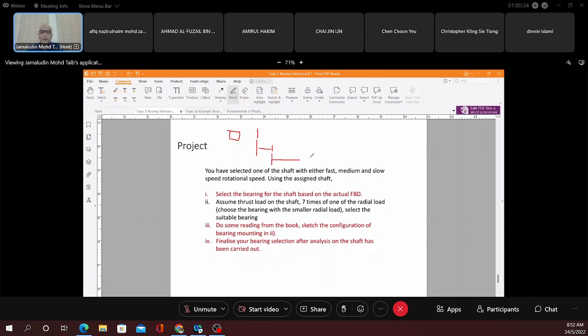For the gear manual calculation, one person will do this one, the second person will do this one. For a group of 3 persons, maybe you can use a different module to test. Let's say your friend uses module 2, or you can choose module 1. Same calculation, but in this case you will have 3 shafts.